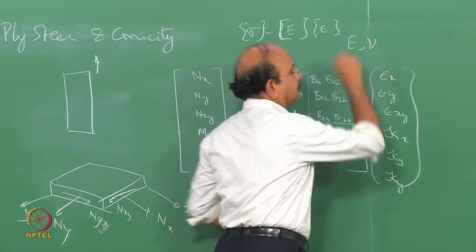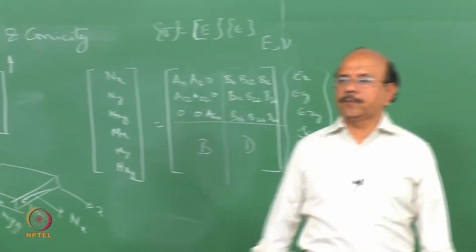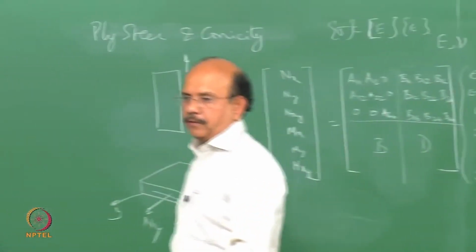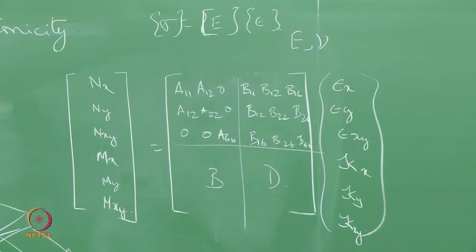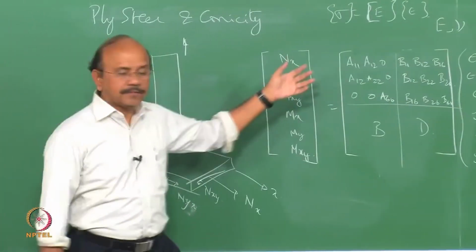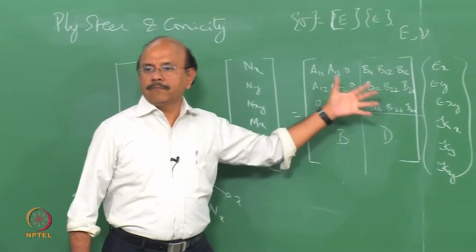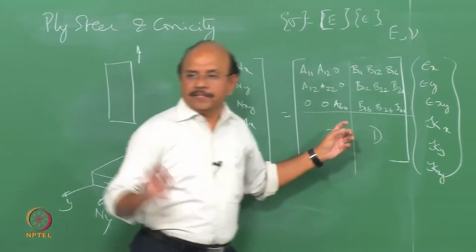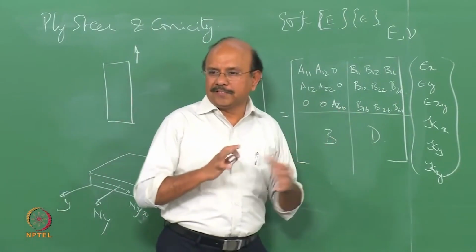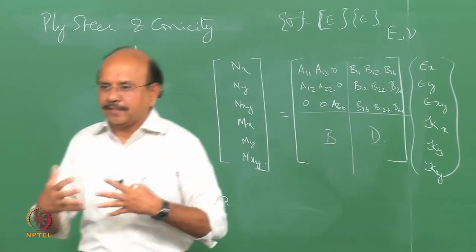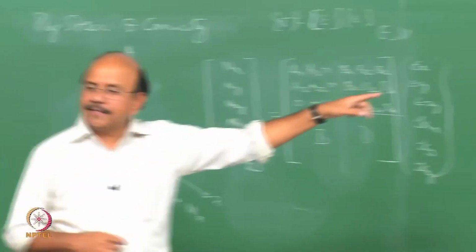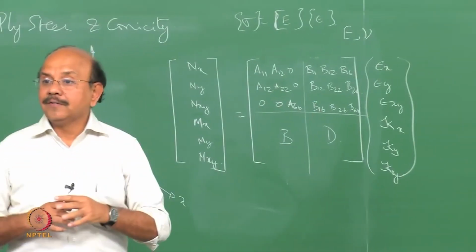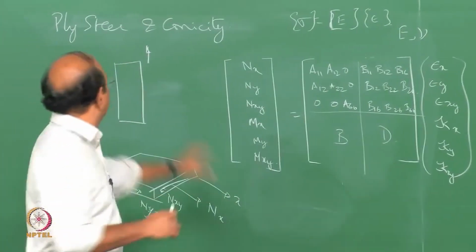So you require two quantities for an isotropic material, E and nu. Okay? Here, this is a laminate, and so this is not an isotropic material. Okay? And hence you have a matrix which is similar to this. That's why I said, let's not go into the details. It's not to explain laminate theory, but to explain why it happens and how that causes what is called as